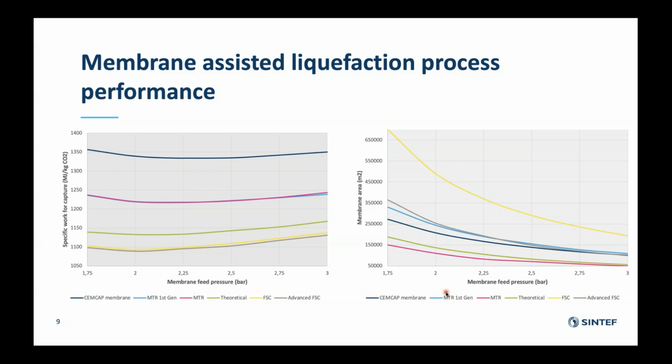Right. So based on this, we cannot say that there is a clear winner. However, we can point to a few facts. Like I said before, a higher selectivity membrane implies a lower pressure ratio required in the compression stage. A higher selectivity membrane also implies a higher purity in the permeate, so possibly lower vacuum pump work is required, and so lower costs.